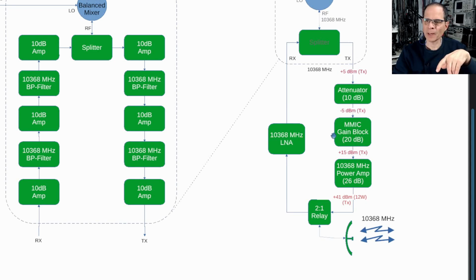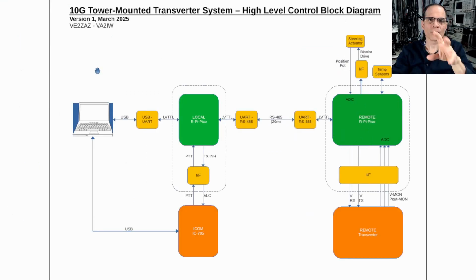Adjusting transmit power, different power amplifier, which you've seen already, and the addition of an MMIC gain block, a small amplifier made in China. It works okay, and it only draws 50 milliamps. So it looks like a good little beast. Time will tell, of course, but for now it does the work. So that's for the RF side of the business.